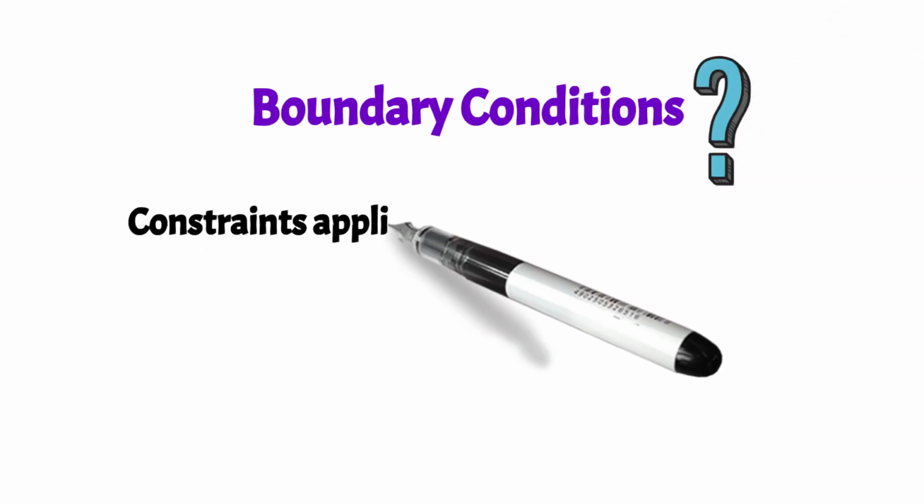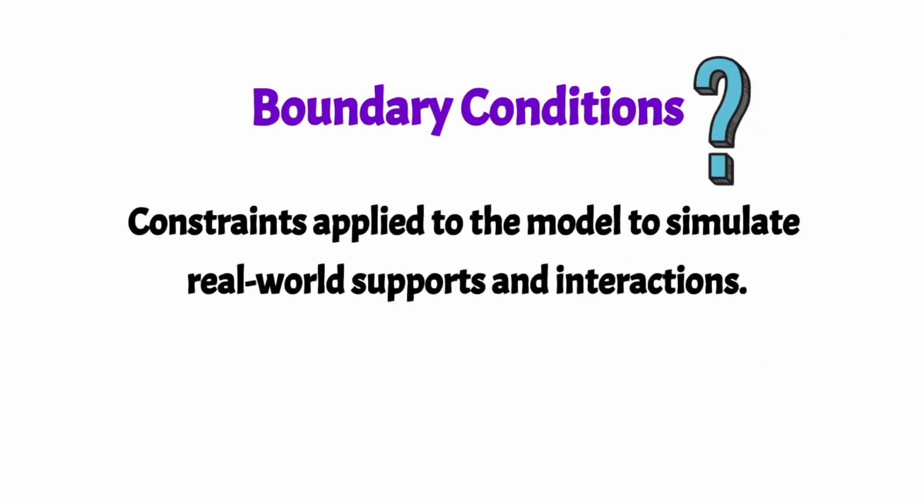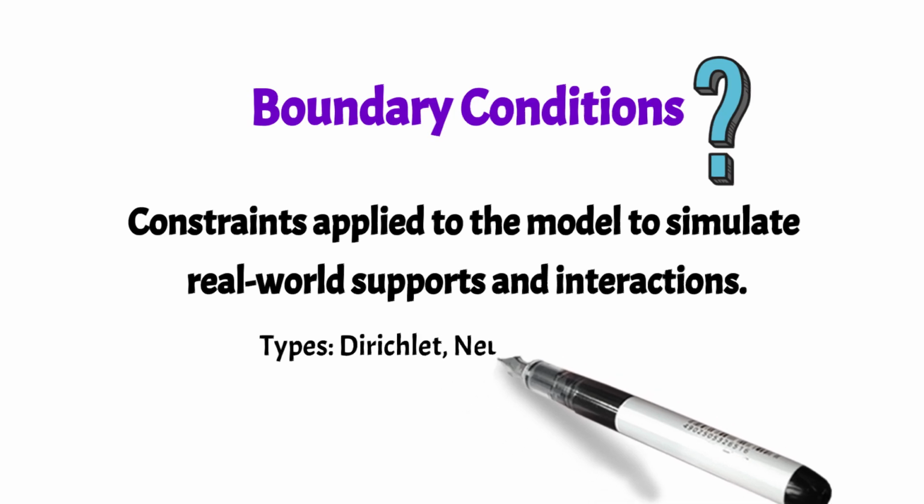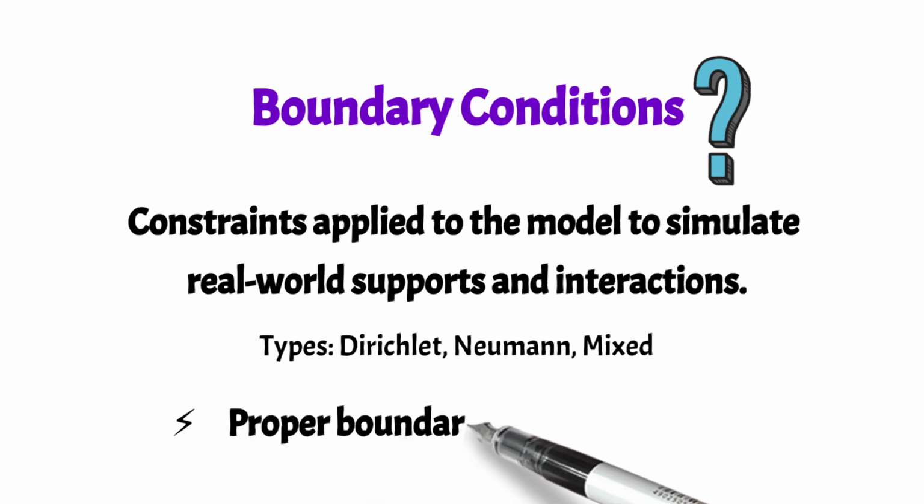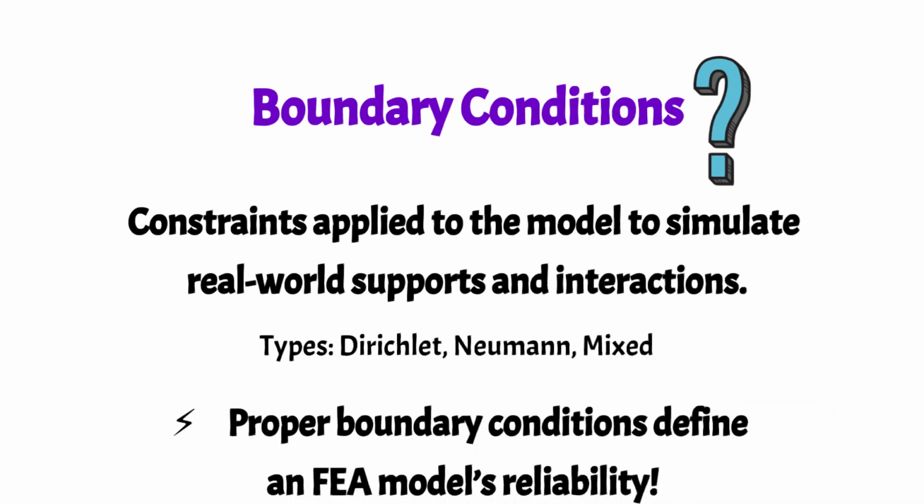Another term you commonly hear is the boundary conditions. They are basically constraints applied to the model to simulate real-world supports and interactions. There are different types of boundary conditions. There are Dirichlet boundary conditions, Neumann boundary conditions, and mixed conditions. These boundary conditions define the finite element model's reliability and play a crucial role in finite element equations.